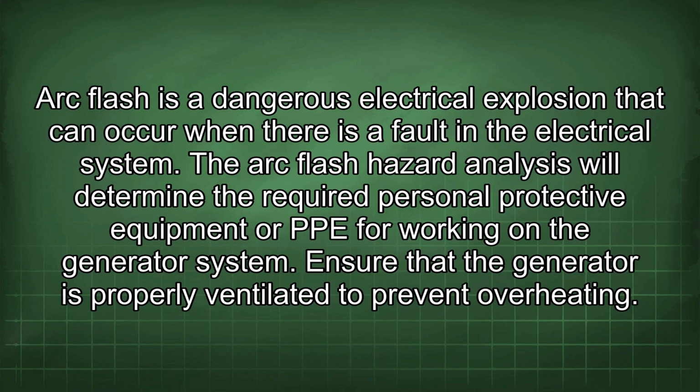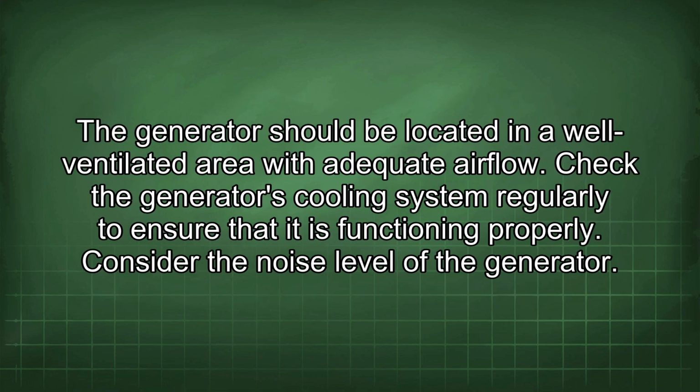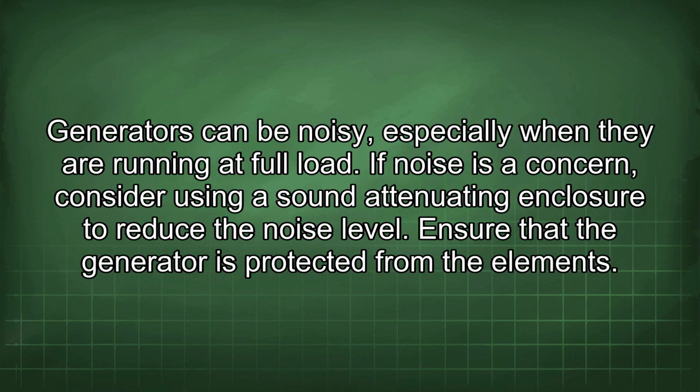Ensure that the generator is properly ventilated to prevent overheating. The generator should be located in a well-ventilated area with adequate airflow. Check the generator's cooling system regularly to ensure that it is functioning properly. Consider the noise level of the generator. Generators can be noisy, especially when they are running at full load. If noise is a concern, consider using a sound attenuating enclosure to reduce the noise level.